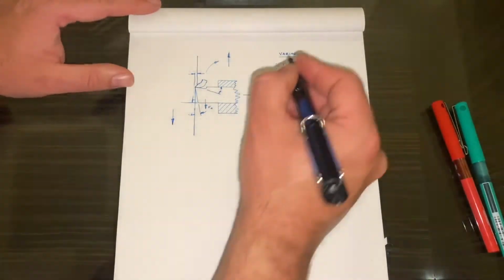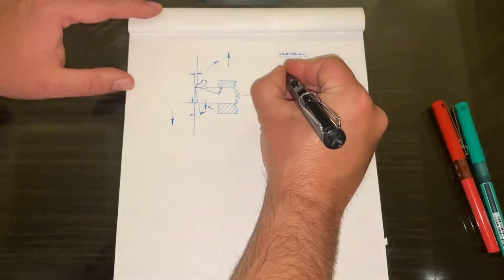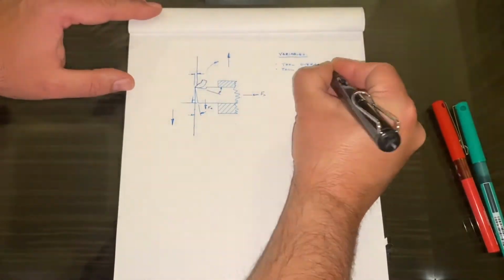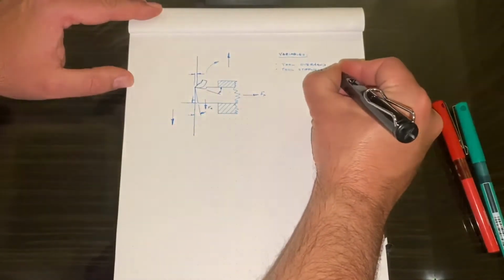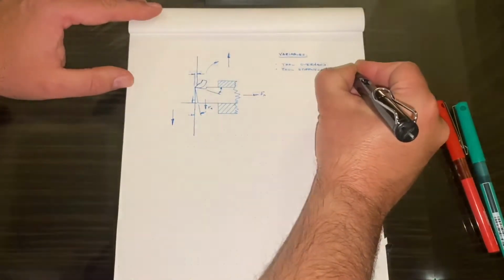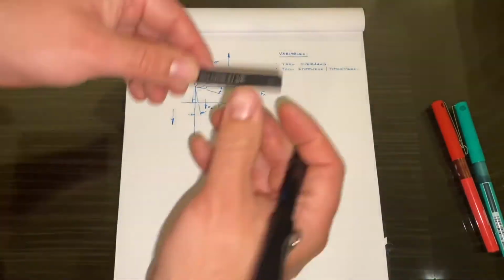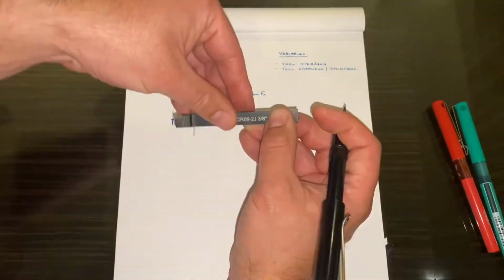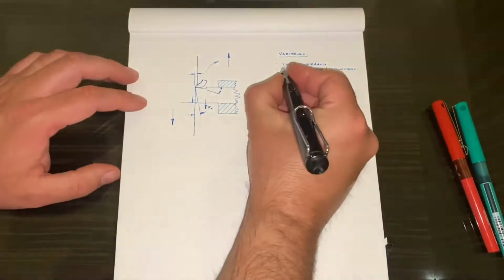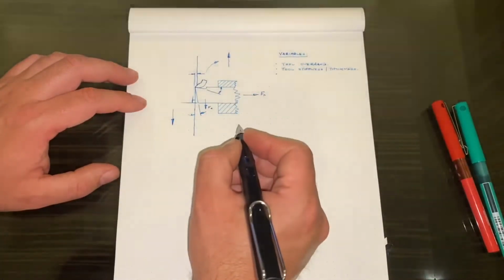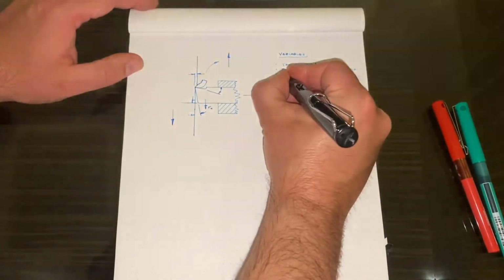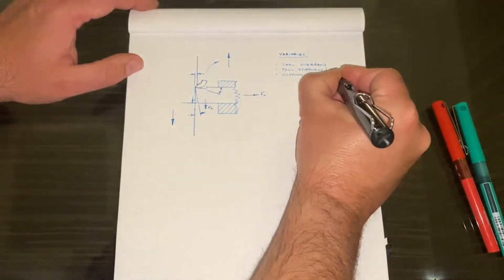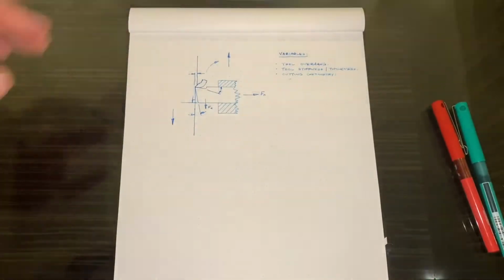The next is the tool stiffness. I'll include thickness with that as well. So the thicker the tool, it stands to reason, the thicker the tool, the stiffer it will be. That's pretty obvious, I think. And then the next is the cutting geometry. So what do I mean by cutting geometry?